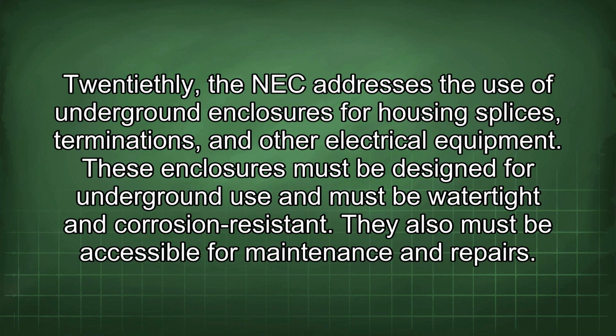20thly, the NEC addresses the use of underground enclosures for housing splices, terminations, and other electrical equipment. These enclosures must be designed for underground use and must be watertight and corrosion resistant. They also must be accessible for maintenance and repairs.